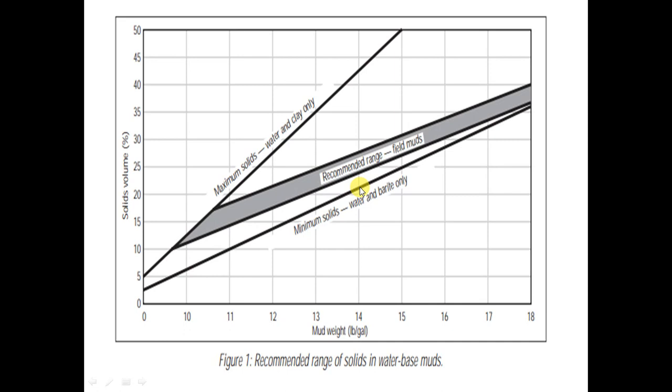If you need to make a solid analysis, but you don't have the simulator or the computer, or you don't have the calculations that are required, this is the graph that gives you a fast figure, or quick information about whether the mud is in the proper range of solids, or the solids are higher or lower. So take care of all of this.